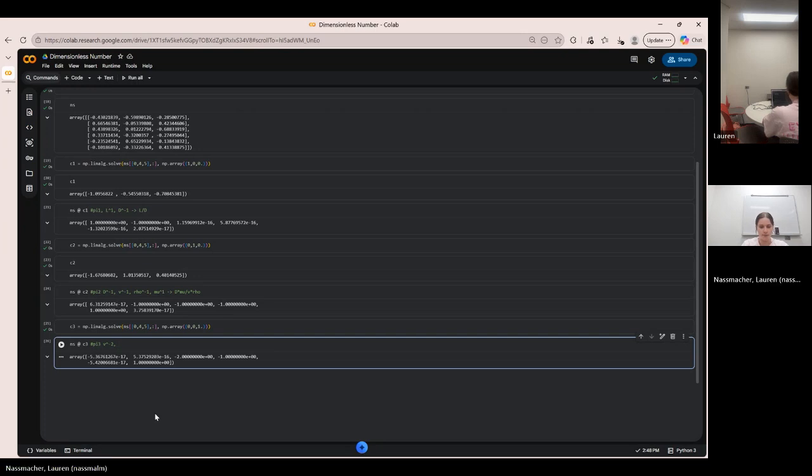Our rho is to the -1 power. Our mu is negligible, our viscosity is negligible, and our pressure is to the first power, or change in pressure. So over delta P to the first power, which means that our equation is delta P divided by V squared multiplied by rho.